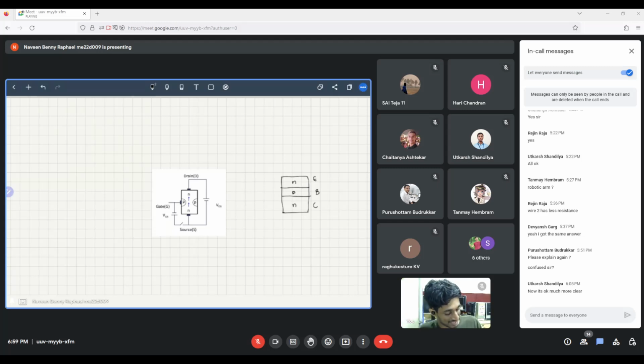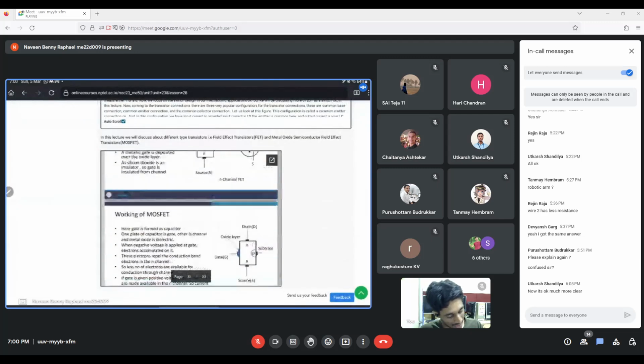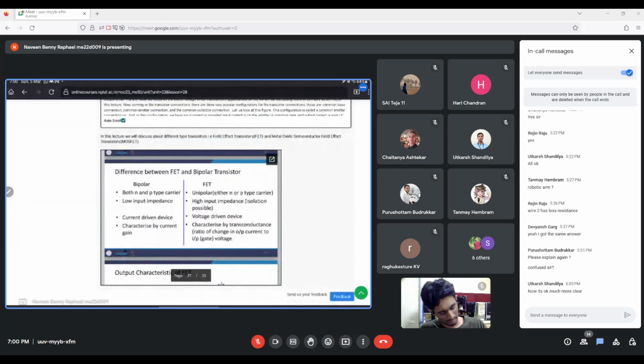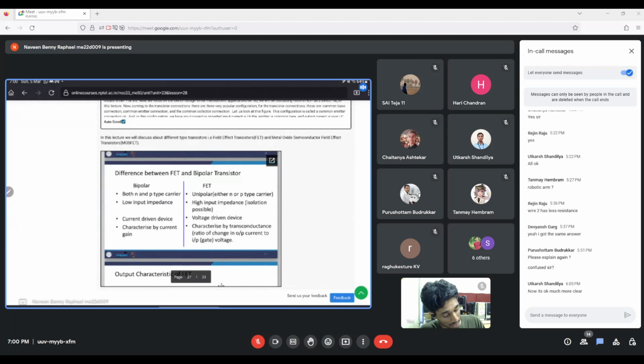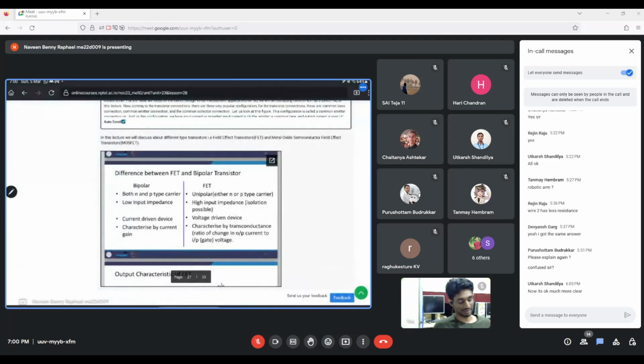They have different architecture in the first place. Secondly, because of different architecture, FETs are kind of nicer than BJTs. One concept which is pretty clear is that FETs don't have a specific direction. You can have the source and drain interchanged, but in BJTs, emitters and collectors have different sizes, and therefore you can't swap the emitter and collector around. So they are different. They're different technologies in the first place.